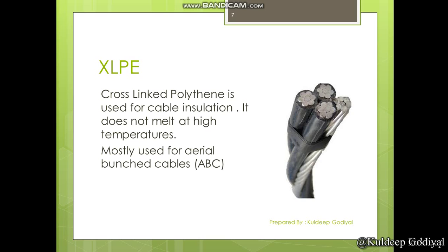The clad cores are generally used for phase cables, whereas the bare conductor, or bare strand conductor, is used for neutral conductor. This is just because of some cost effectiveness. If we are able to pay, you can clad the fourth cable, that is the neutral wire, also.